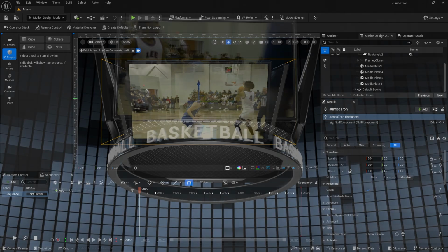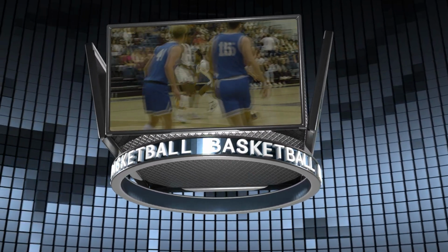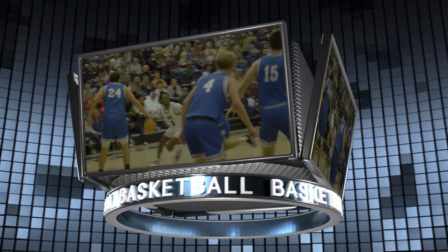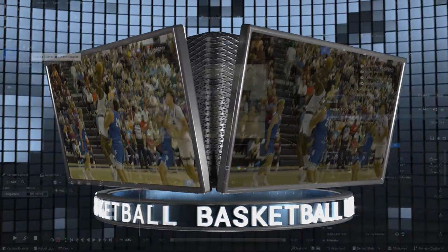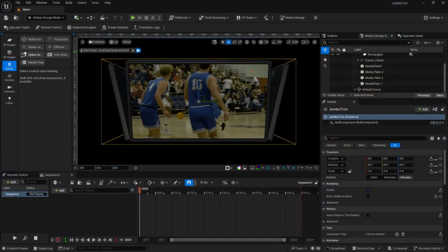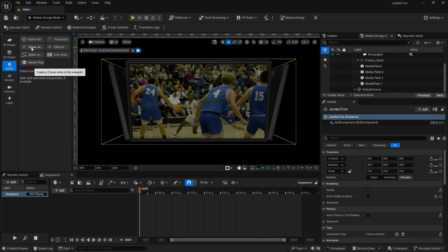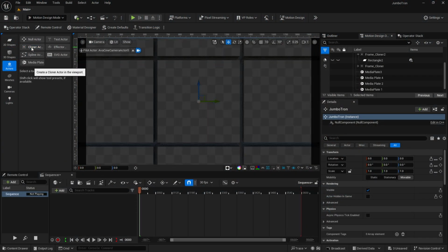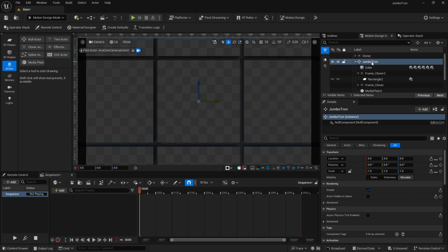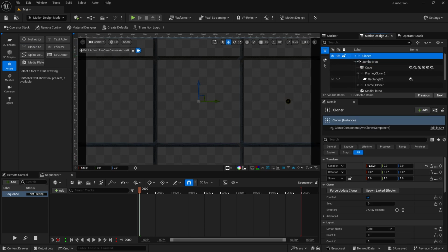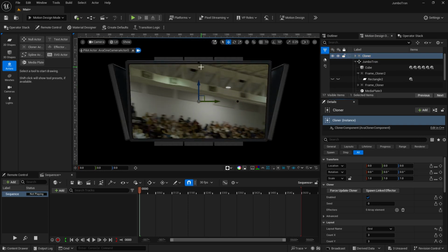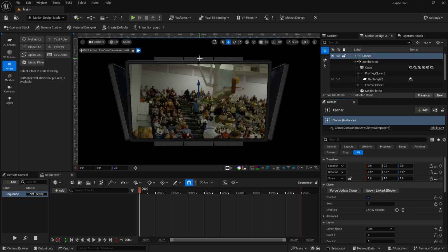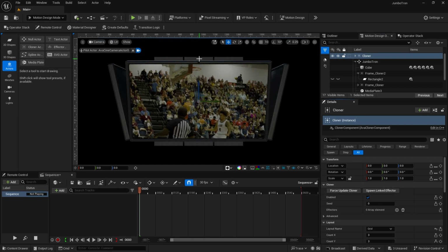plate back in. So taking a look at that original animation now, I want to add in the back wall. To do that, we're going to use a cloner. And so I'll go over here to my actors, and I'll go to cloner and double click on that, drop that in, and let me reset, make sure that everything is reset on that. Select it and reset location. My cloner is still back there, and we're going to make some adjustments to it.